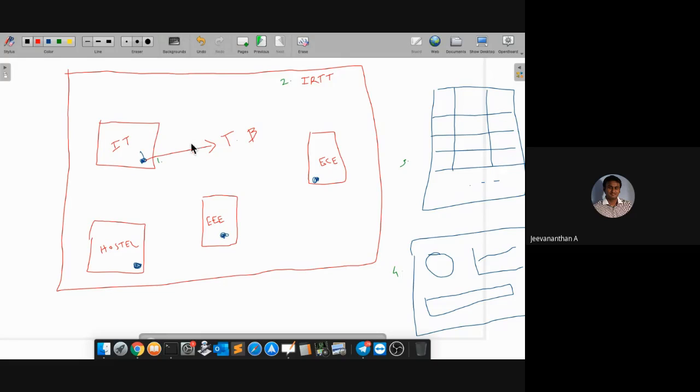Right. So now, how you connect the devices to the ThingsBoard. That only I talked about, the microcontrollers and all, right? So here you'll be placing your microcontroller. That microcontroller may be, say, a Raspberry Pi. So the Raspberry Pi will be connected. By using any Python code, you'll be pushing the data to ThingsBoard. You got it? So from your Raspberry Pi, you'll be writing some Python code, and from the Python code you can send your sensor data to ThingsBoard.